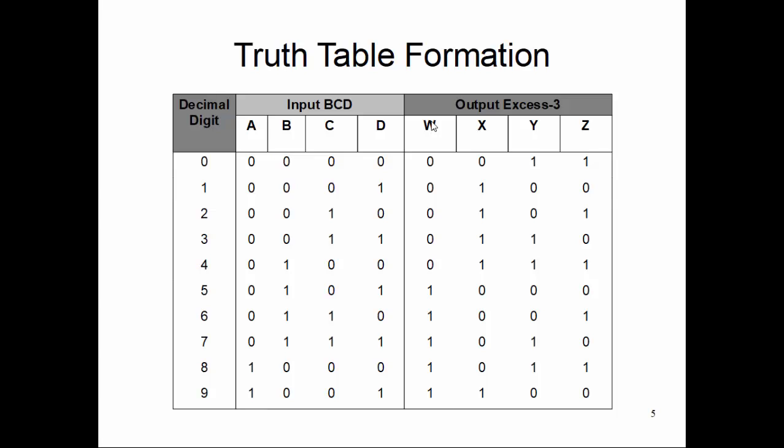Now let's explain this. For this problem domain, you see your expected input bit patterns are bounded from 0 to 9 because we are dealing with a BCD digit, a 4-bit BCD digit. That means at my input side, I don't expect any bit pattern corresponding to 10, 11, 12, 13, 14 and 15, just by the problem specification.